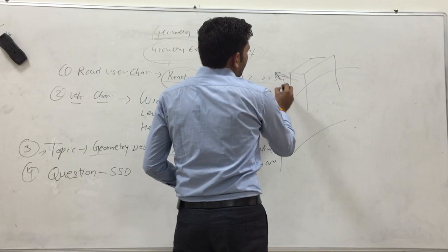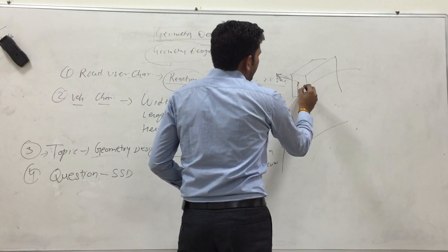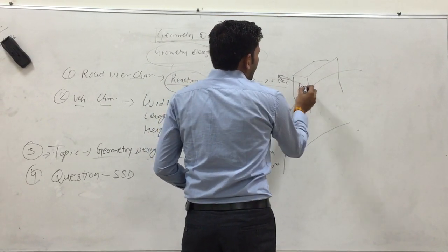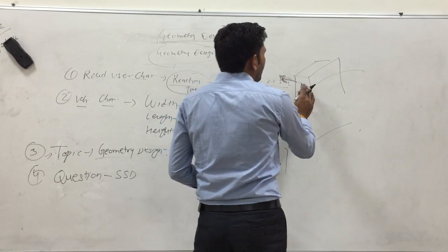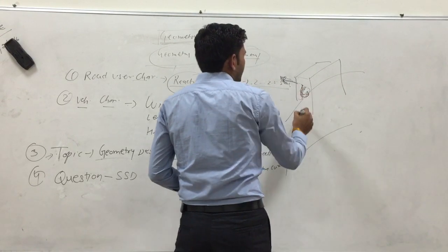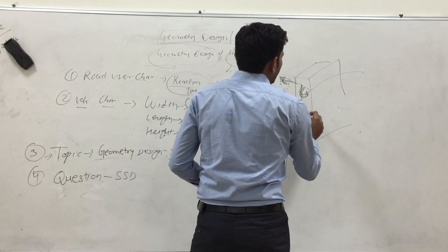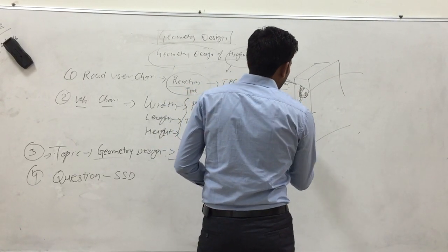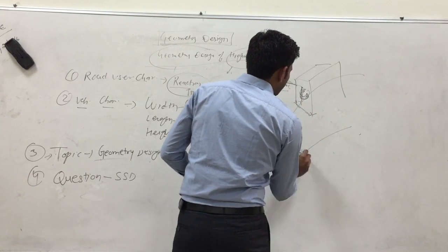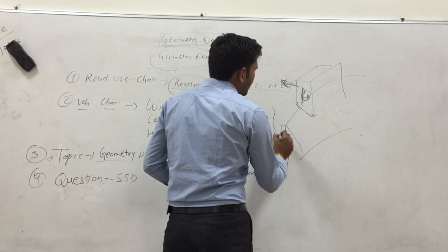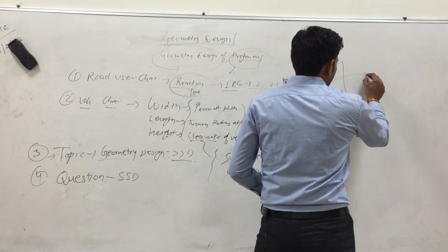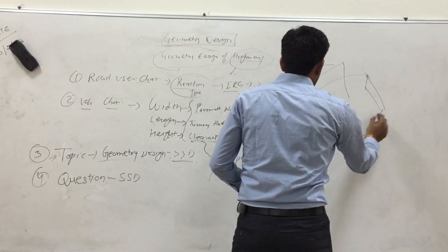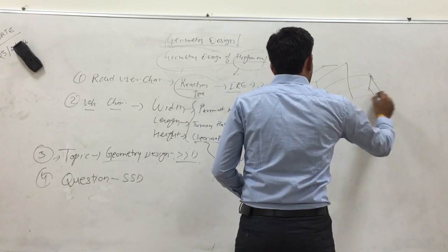If the height is more, then it can overturn the vehicle, and to reduce this force, we increase the height at the outer side, and this is super elevation, provided at horizontal curves.